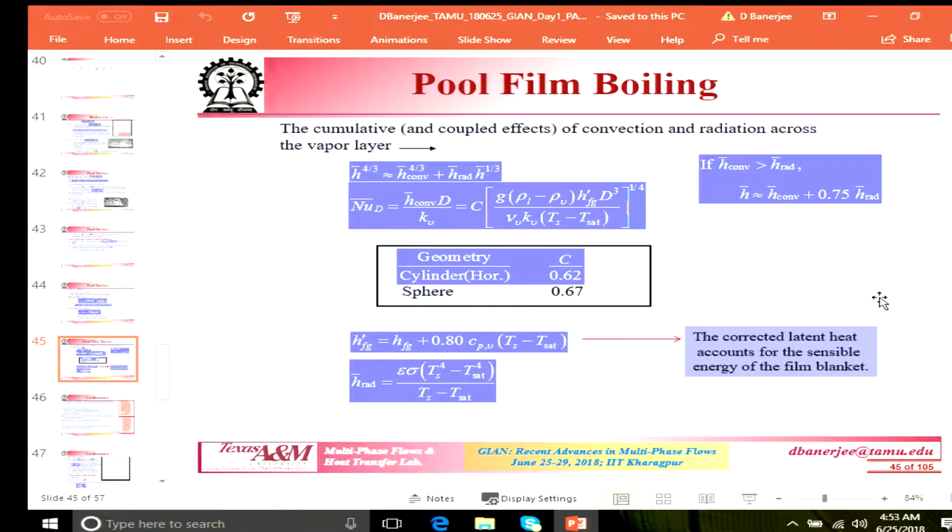So, when you design a boiling experiment, you have to pay careful attention to the size of the heater that you are using, and this is a very common mistake that people make very often in the literature. In other words, if I have a small heater, I will actually get a higher heat transfer or heat flux, everything else being the same. Does that make sense?